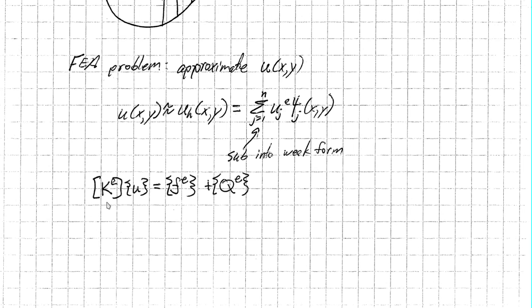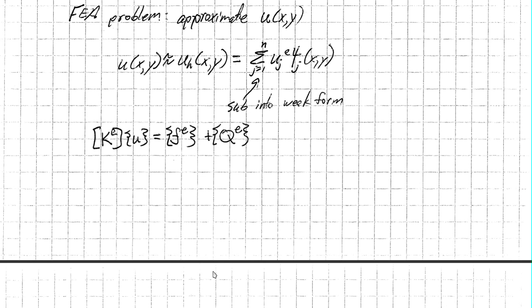And what this will end up looking like is a matrix equation. K, here's your nodal solutions. At every node you may have some internal source terms, like I mentioned, maybe internal heat generation, and you may have heat transfer on the boundary.